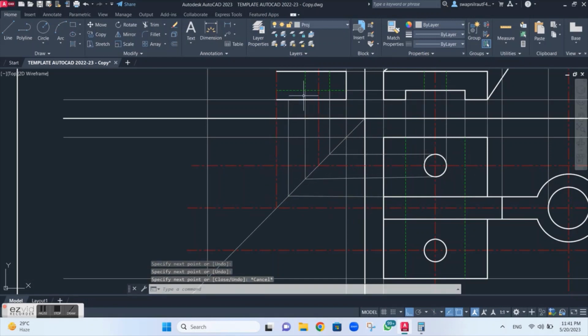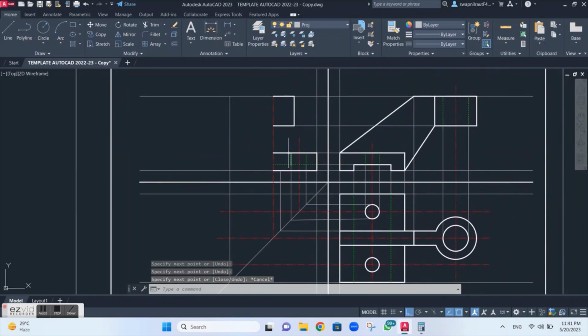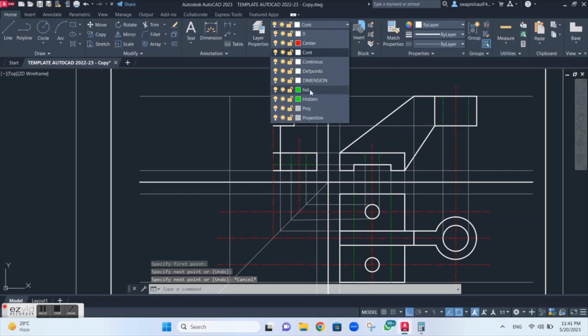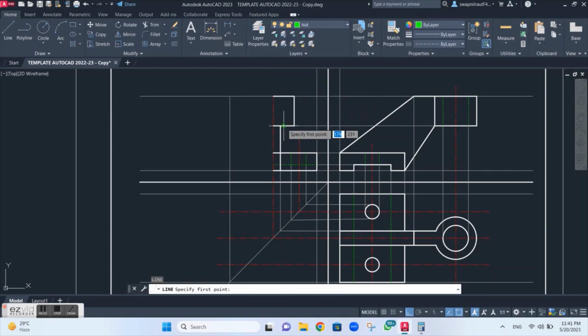Okay, now if you observe carefully, for the rib there are two parts. The line over here, this rib portion is clearly visible to me. So up to that it will be a dark line. So here I will take from this part up to this part, a dark visible line for the rib portion. So for this much length I will draw a dark line of the rib. But there is one more rib portion at the behind part for which it will be hidden. So I will draw a hidden line for the remaining rib portion. Now why is this hidden? Because